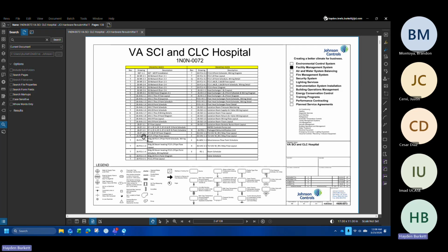And then we go into all the different variations of fan coils. This includes 2-pipe, which is, I believe, just cooling only, followed by 4-pipe, which includes steam heat, as well as the variations in points being provided. Then we cover the site's heat exchangers. This is a pair of heat exchangers that serves pretty much anything that uses hot water on site. There's a pool heat exchanger, which is for the therapy pool.